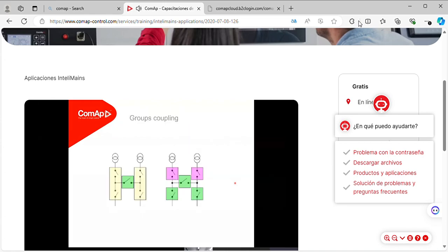So as you can see here, we cannot do grouping between utilities because I do not influence the voltage and frequencies between two different substations. So this is not possible, but the second one is possible, where you have influence between the two genset groups or two buses, where I can influence the voltage and frequency to match. On the top end, I can just transit from one utility system to the other utility system.